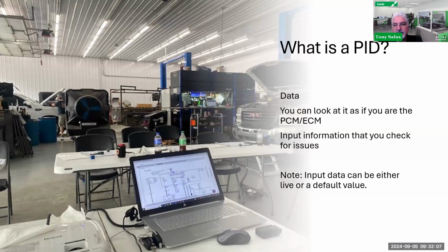Well, it turns out that the coolant had heavy electrolysis. Upon putting a meter in the coolant, I found I had way over 8 volts. In other words, there was so much of an electromagnetic field around the coolant as it was circulating that it influenced the crank or cam sensor, which in turn caused a misfire. It's not very common, but it has been known to happen.